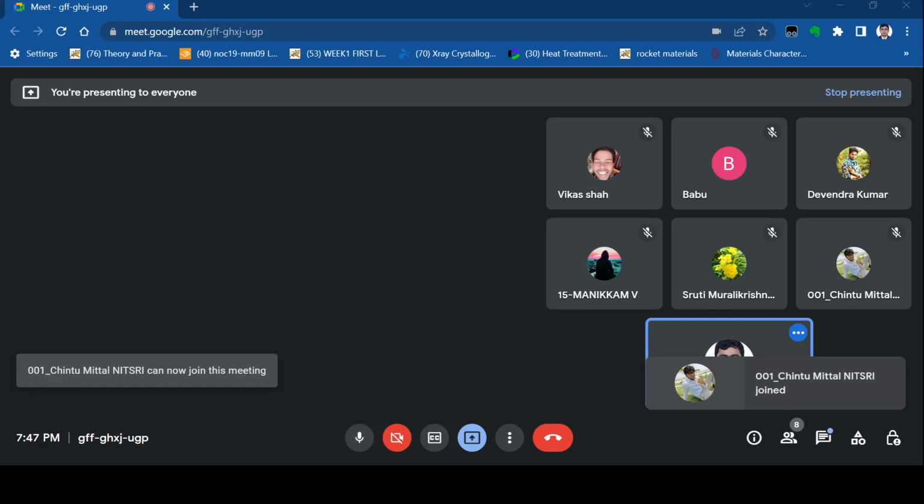T2 is smaller, so relatively delta T will be larger as compared to T1. So this will be in the middle. And T3 is the lowest temperature, that means highest undercooling. Undercooling highest means delta GV highest, delta GV highest means delta G star lowest. So this is a small value.